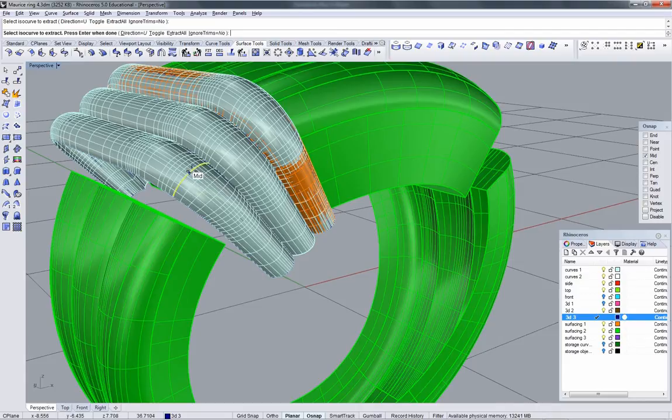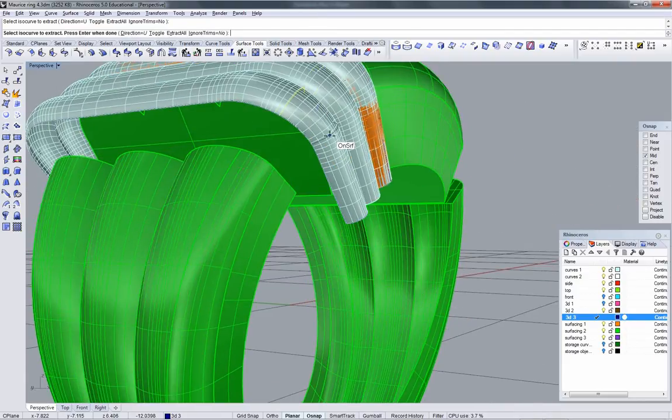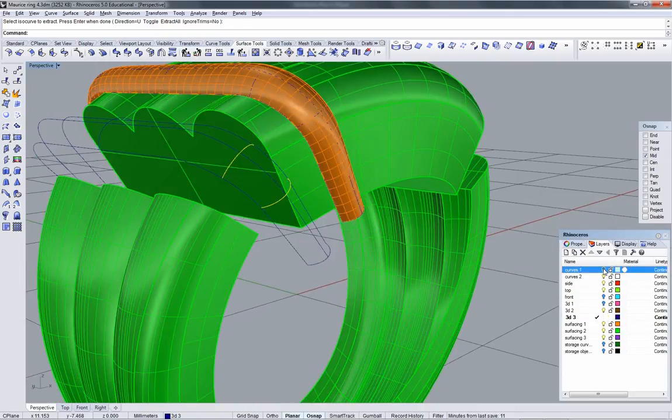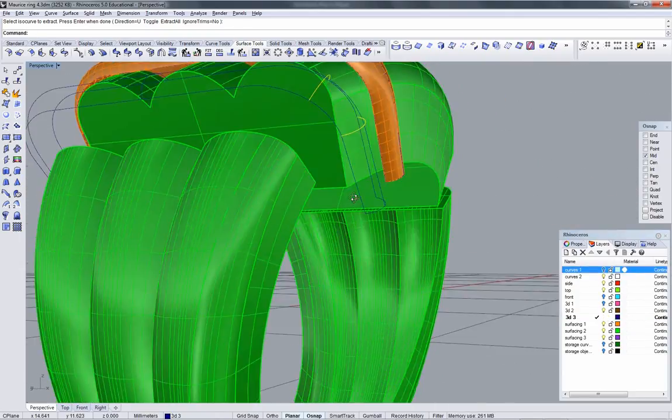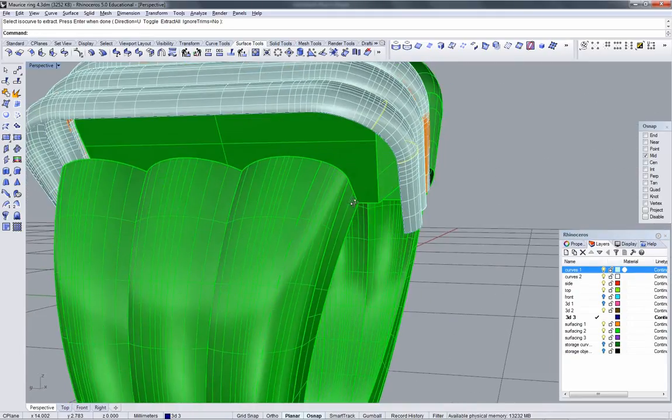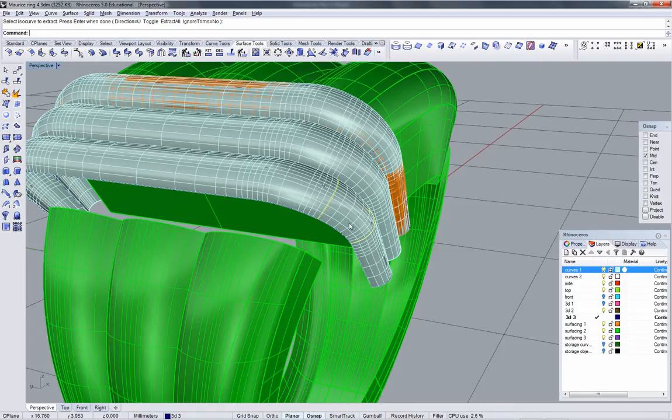To handle this, whenever you have a sharp bend, you want to have additional cross sections to control that. That's just a basic modeling strategy for swept surfacing. When you're going to do a sweep like that, especially a long linear sweep, and you have a kink or a tight bend, you want to have plenty of cross sections.